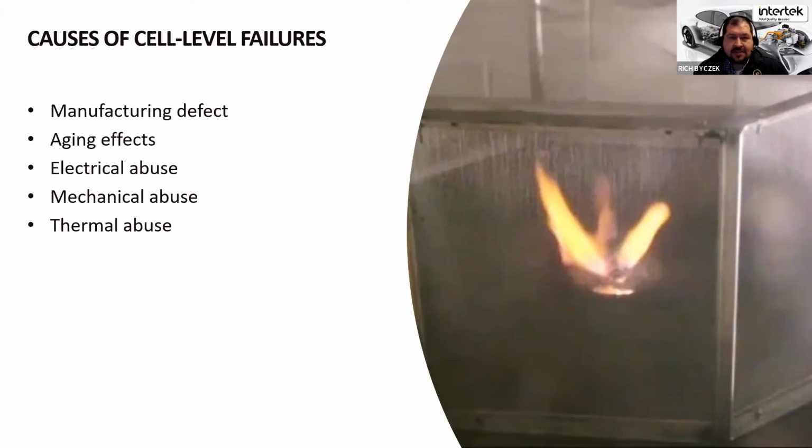Next, electrical abuse. This is talking about usage cases. Typically, we're concerned with things like an overcharge event, meaning excessive voltage or excessive current inflow to the battery for charging, and then outflow in terms of short circuiting or over discharging events, where you drive the battery beyond its 100% stated charge and down below its 0% stated charge.